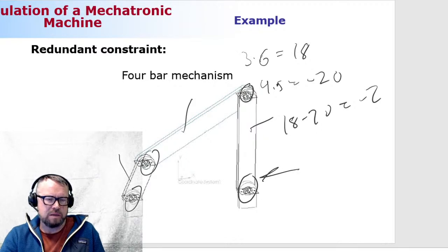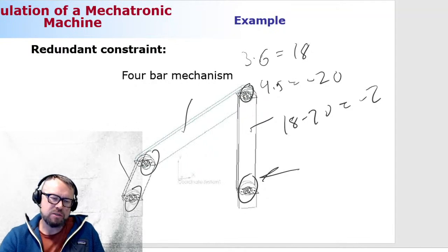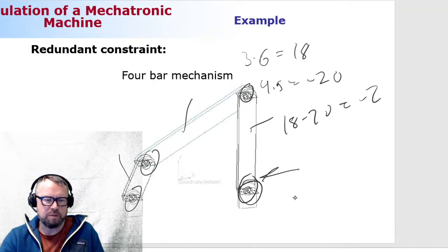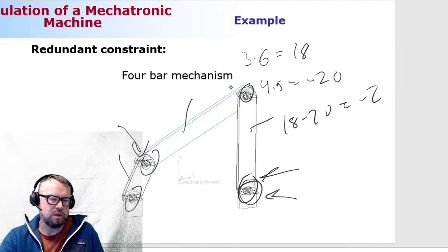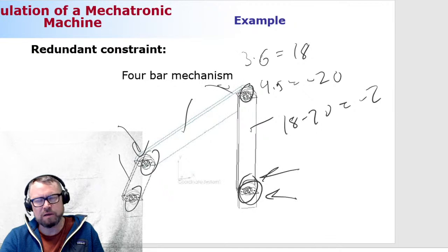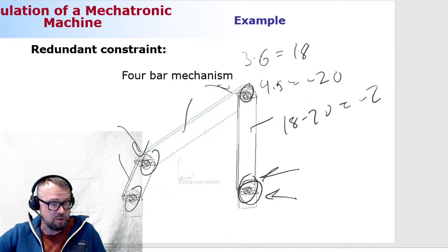It is redundant because the motion of the plate is too constrained. To get rid of this, a joint could be replaced by a primitive joint, or you can use a cylindrical joint in some other location. Those are the ways to make this system have 1 degree of freedom. So that was just a demonstration to you.